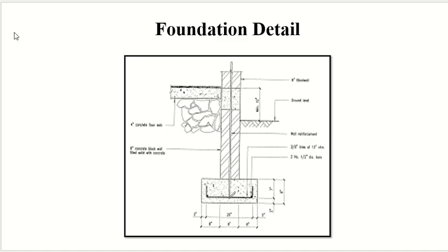Now you can see the connection between the foundation and the column, and the connection between the column and this wall beam as well. You can see what type of reinforcement and what material we are using, how long this steel will be, and how much steel of the column will go inside the foundation. That's why I said it will give you more precise, more accurate details.